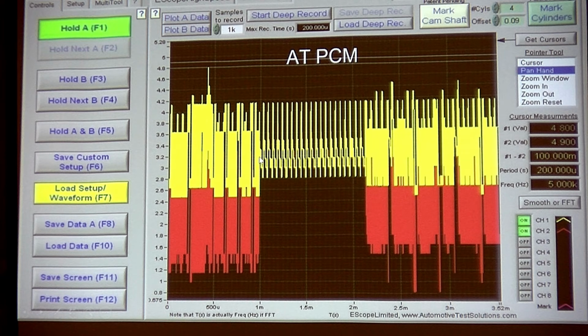So what's that? That's ringing, guys. I'm ringing. And the ringing is giving me all kinds of codes. Remember how all these modules are saying they're failing and they can't talk? Well, when I'm ringing, that ringing sets another bit, and that bit is what? It doesn't add up in the cyclic redundancy check, and it's going to flag it and say that it is no good. We destroy the message, and then that counts 8 points against the guy who sent the message. Do you start to see how this is counting and how this is working?